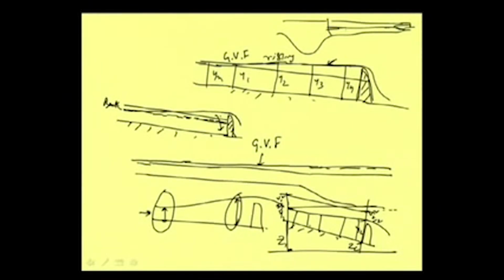So, we will have to construct some marginal embankment, or on the side we will have to raise this bank. This is the bank level we will raise. So, to what extent? Suppose we know at this point our bank height will have to be this much, but we need not carry the same height up to this point, because water is rising from this point. So, we know that from this point the water level is crossing the bank. So, we can increase our bank height like this, and that way we can save our expenditure in raising the bank, and we can achieve economy in such projects.